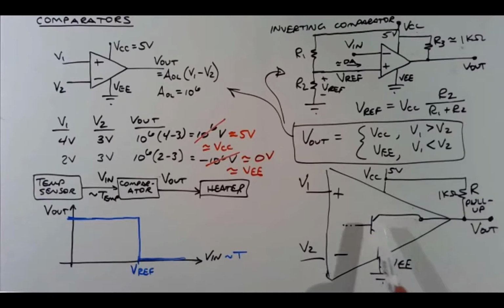this chip is actually either saturating that transistor, which means 0.2 volts or less between ground and the output, that's a low output, or this transistor is in cutoff. And if the transistor is in cutoff, that's like an open switch and the output goes high. You will see this referred to as an open collector output.